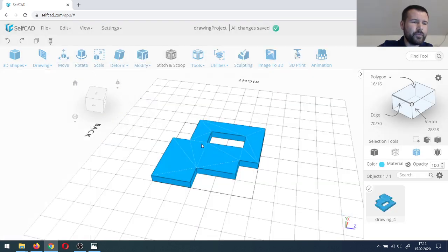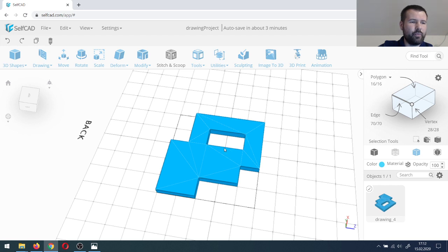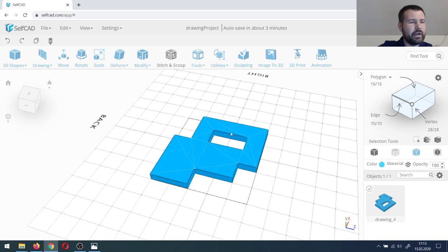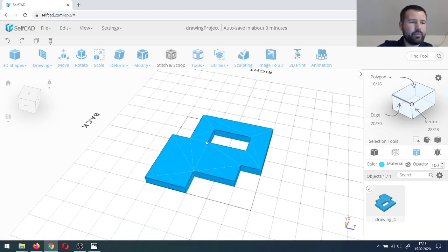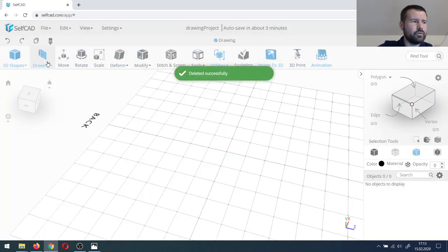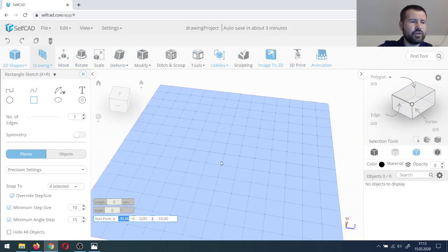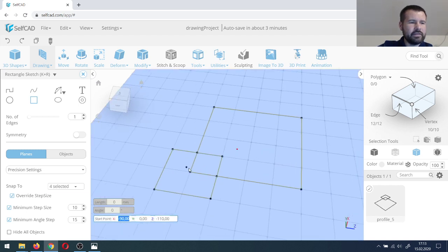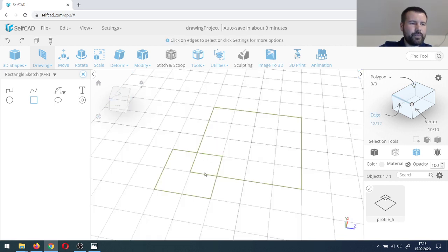If I finalize this, you will notice that there is this small hollow part which you can actually end up with by finalizing the freehand process. On the other hand, if I would like to do something like that in 3D Sketch, if I draw the same shape and now if I add the intersecting rectangle, you will notice that those two solutions actually did not strictly get joined together.